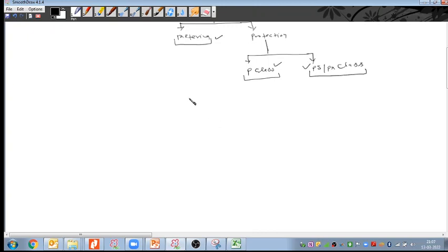Let me draw the CT, the current transformer, the drawing that we have seen in college time. Here is my incomer bus bar, then the breaker, and then it is going to be CT1. If we take one winding, or at most two windings, this is primary P1 and then P2 here, and it is going to a load. Suppose the load is my transformer. This is the symbol for mutual coupling, and the CT secondary side has a very huge number of turns based on the current ratio we take.